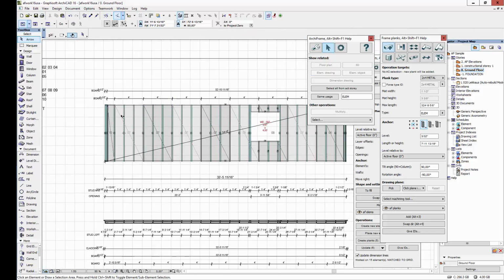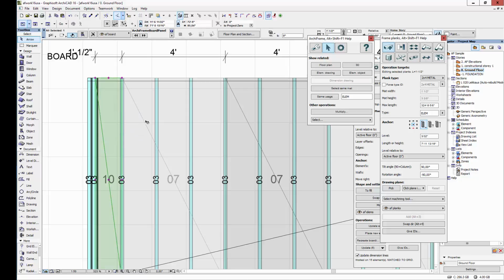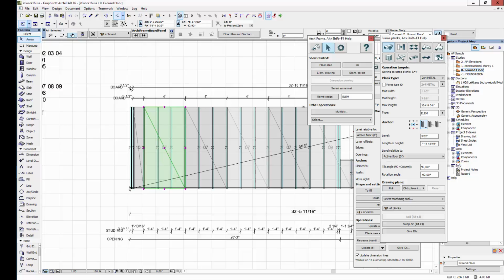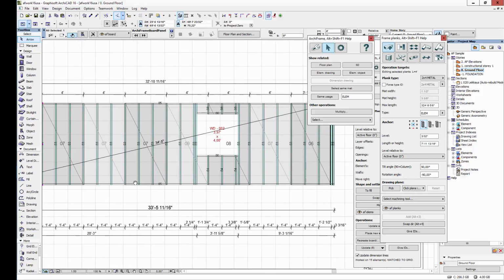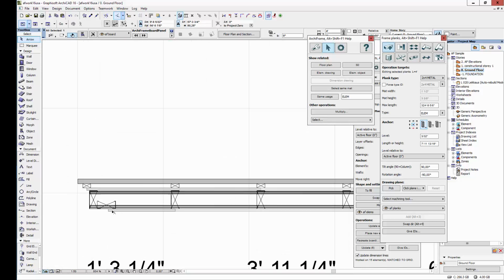This topmost projection is looked from inside, showing the boards and the main framing. There are dimension lines for the board offsets relative to the main framing, the board division, the stud from mid to mid here, and in this top elevation we have from left to left. And some markings for the openings. Then this is the top view.